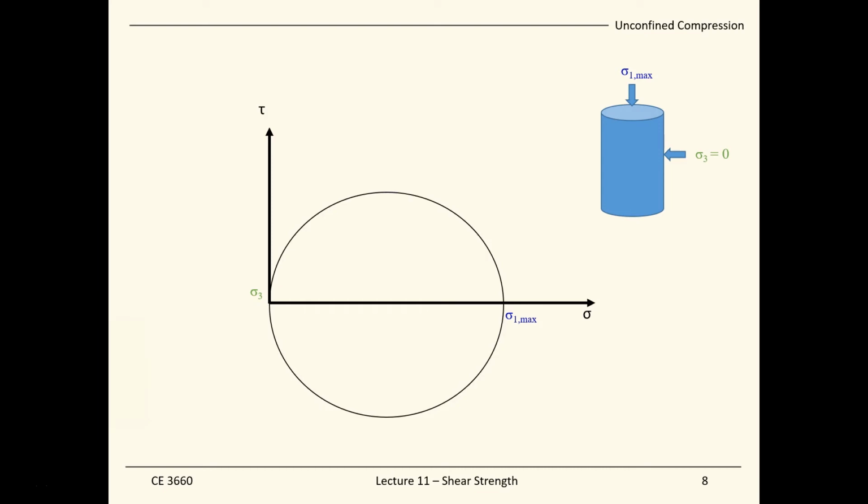So with this Mohr circle, the failure stress is, well, before that, let's find the pole for this Mohr circle. Remember one more time from the Mohr circle last lecture, the pole method tells us that knowing 2 of these 3 items, the pole, the stress points, and the orientations, you can find out the 3rd one. So now we want to find the pole. That's why we look into the stress points and also the orientation, which is the plane.